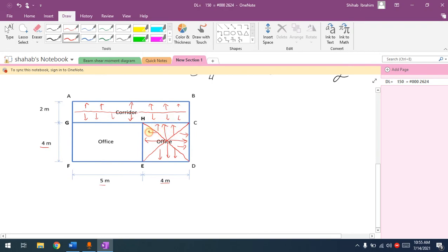And this is this one. For this, which is 4 by 5, we said from the short side you will start, and from the short side you will draw the 45 degrees. They will meet somewhere. They will not go from corner to corner because it's a rectangle. And from the other short side you will draw something like this. Remember, please, you start with the short side, then you connect them along the long side.